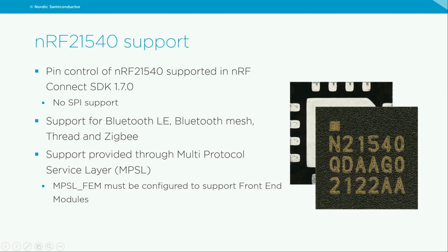So to be able to demonstrate how this works, we are going to release something called the... we are using pin control, as I said, in 21540. There is no SPI support as of today. Adding the SPI support for setting static gain and so on is something that can be done on the application layer, but we will not be supporting using SPI control for changing between RX and TX mode, for instance.